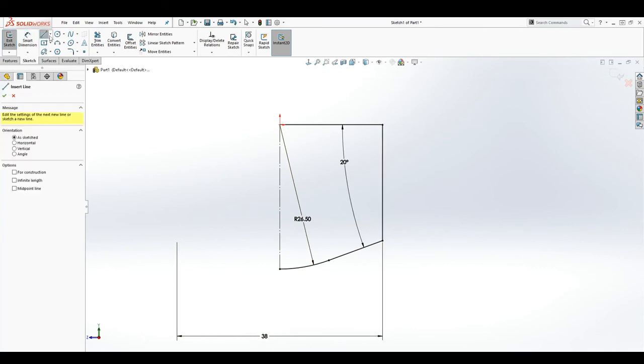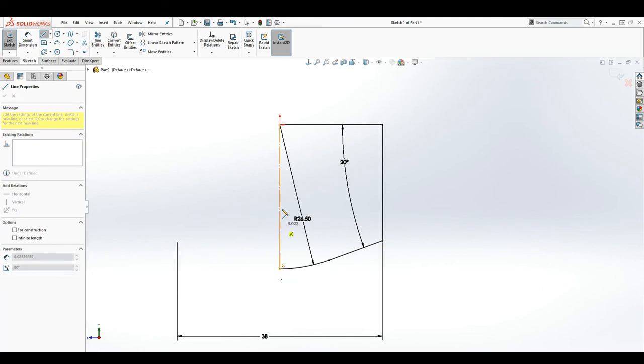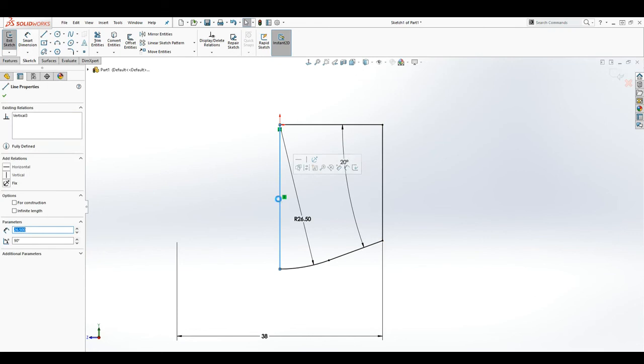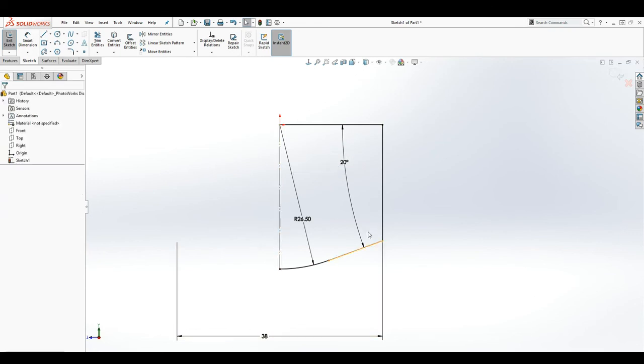And now let's draw a line here. And another thing you need to keep in mind is, before you can revolve, your sketch must be closed, meaning you need to have all this sketch all around. The construction line is just something we use. Like I said, you can use it to aid your sketch. I use the construction line to get the 38 diameter.